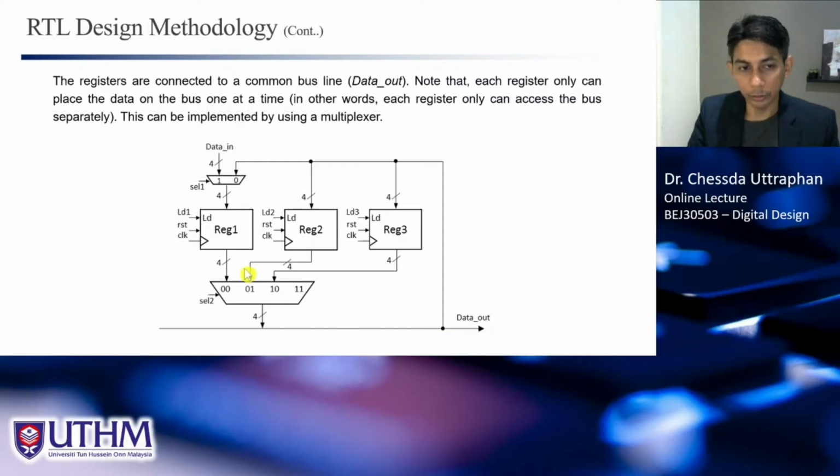So to avoid that, you need to have a multiplexer here, such that at one time only one goes to the bus, whether this one, or this one, or maybe you have others. Because you have three inputs and one output, you need to use a 4-to-1 multiplexer. But of course this input is not used. We don't have a 3-to-1 multiplexer, remember. If you have only two inputs, you can use a 2-to-1 multiplexer. In this case we have three, so we need a 4-to-1 multiplexer.